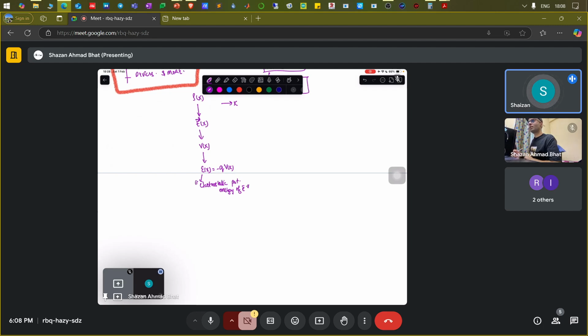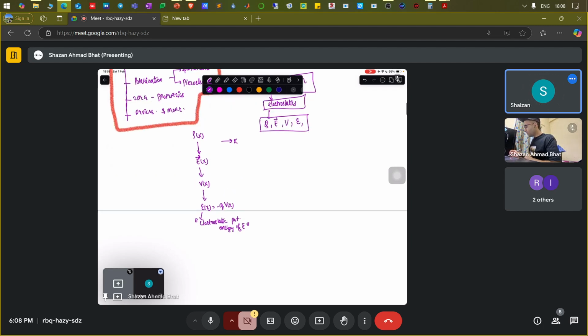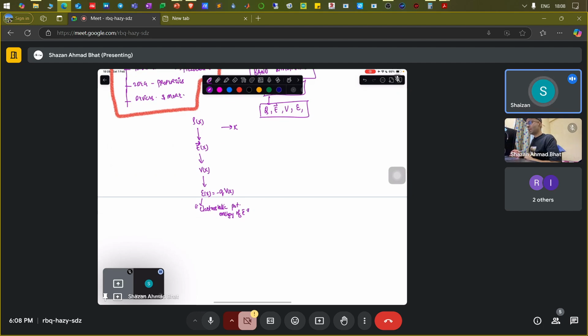So whenever you draw an energy band diagram, be it for a simple PN junction, a MOSFET, or a MOSCAP, whatever you draw, the y-axis is always drawn as the electron's electrostatic potential energy.